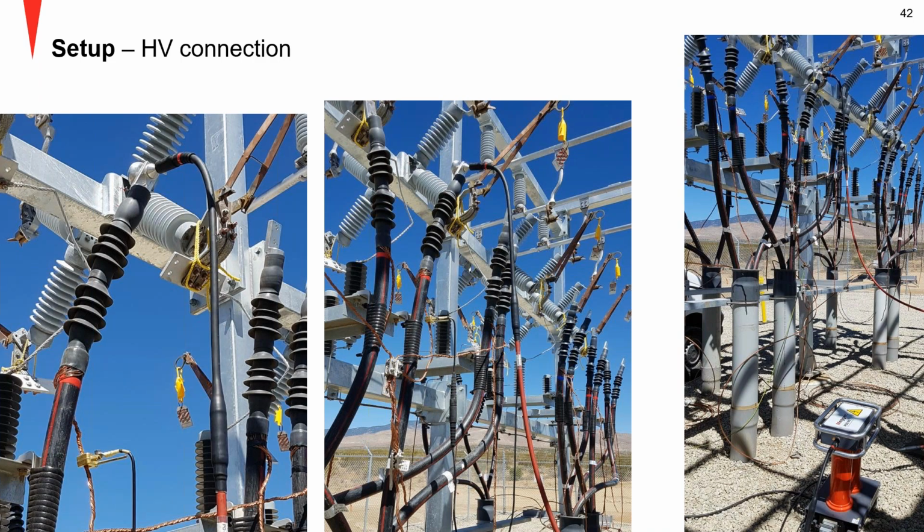And then we have another example here in the field. You can see, again, there's the coupler, the high voltage cable comes out, and then you can see in the middle picture how it is connected to the end termination there. Again, suspended in the air, not touching anything, so the field around it is not distorted. On the very top there, you see some corona preventing add-on at the very end. It's kind of like a spherical add-on that you put on the connector there that prevents spitting and corona.